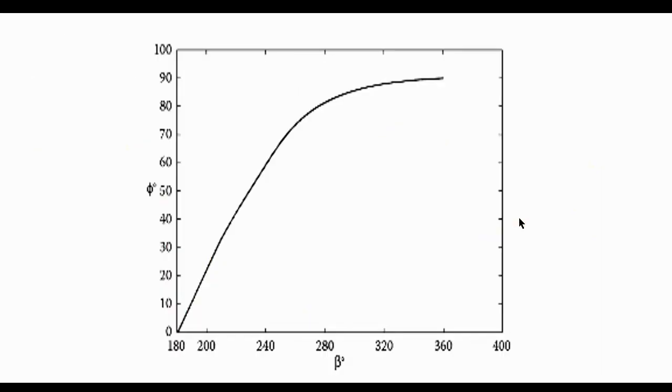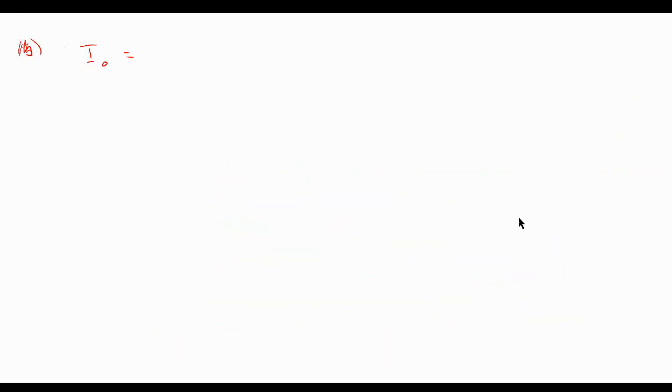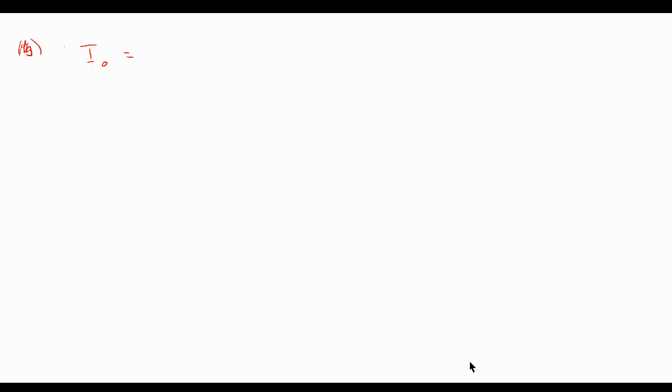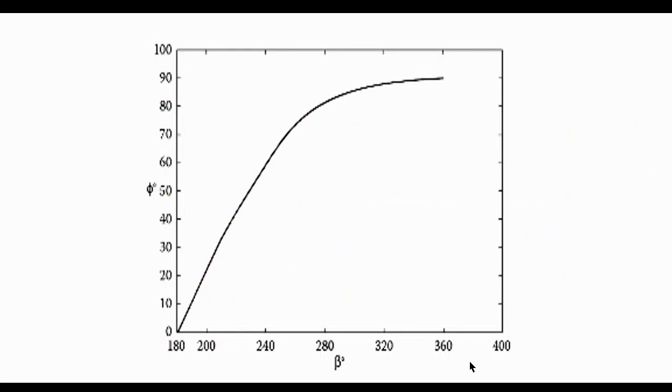Remember, I gave you a method whereby if you have this expression here, and you want to find your extinction angle, you set this equal to 0 and use some numerical method. But then I showed you a graphical technique, so you didn't have to go that route. So it's alpha. After you get that angle, you come here on the graph and find out what beta is equal to. What do you get?